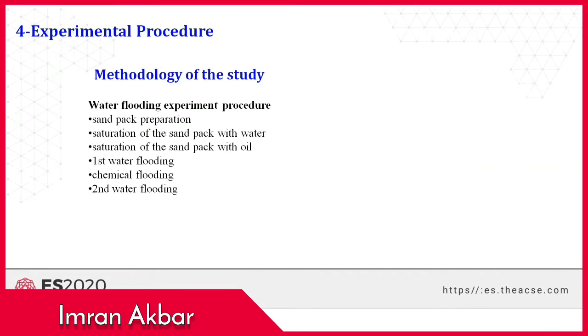Experimental procedure involves water flooding. Number one, sand pack preparation, saturation of the sand pack with water, saturation of the sand pack with oil, first water flooding, chemical flooding, and second water flooding.